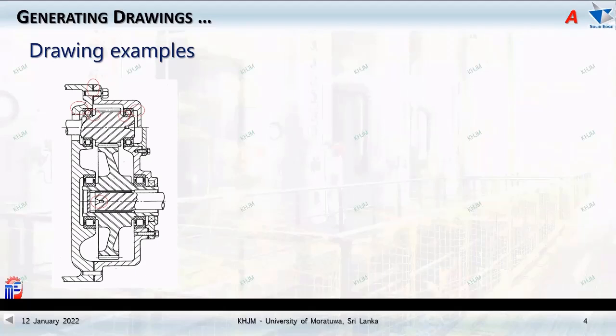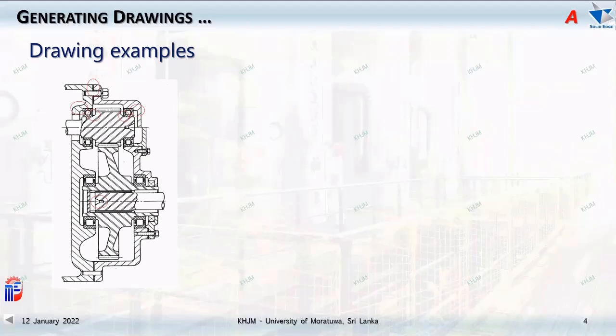Because you can't make all these things exact. Remember, everything ends up with certain tolerances. The bearing will have certain tolerances, the end cap will have certain tolerances. So you will never be able to get all these things equal. So you have to think of all the possibilities. That is why we have put a small gasket over there, or maybe a seal. Otherwise, the oil can squeeze through that particular place.